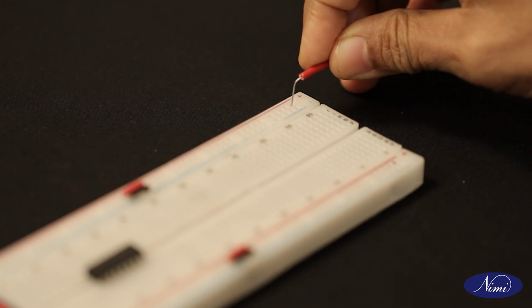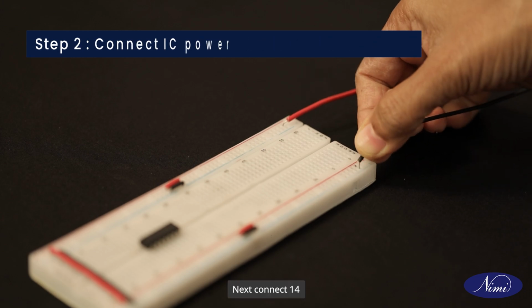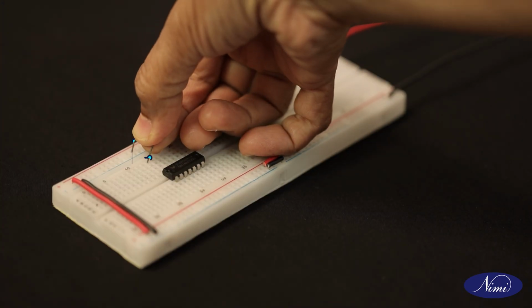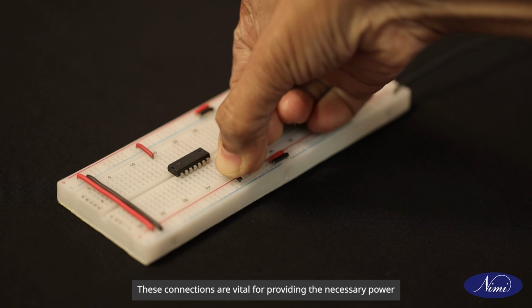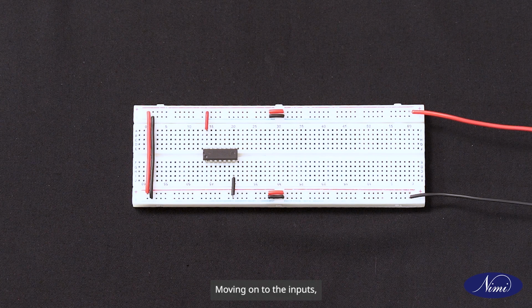Connect linking wires from the power supply to the breadboard. Next, connect 14 pin of the IC to the plus 5 volt power supply. Then, make sure pin 7 is connected with the ground. These connections are vital for providing the necessary power and establishing a common reference for the circuit.